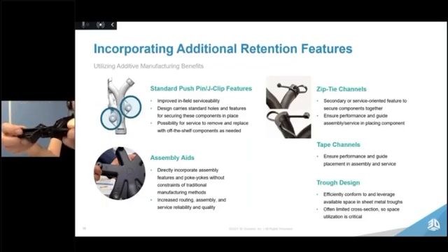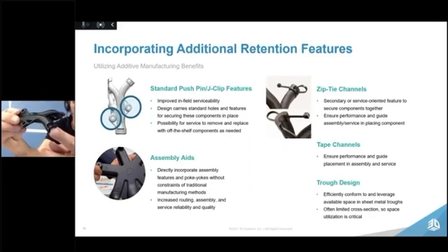This case also gives you an example of a method to secure the harness via channels that house zip ties. So if I can show you this carefully on the camera, you see at each of the ends of the guides here, there are some channels which are designed for zip ties. But that's just one simple solution that can be manipulated to suit the environment and application that takes into consideration the assembly workflow and servicing requirement, for example, for ease of use and accessibility.